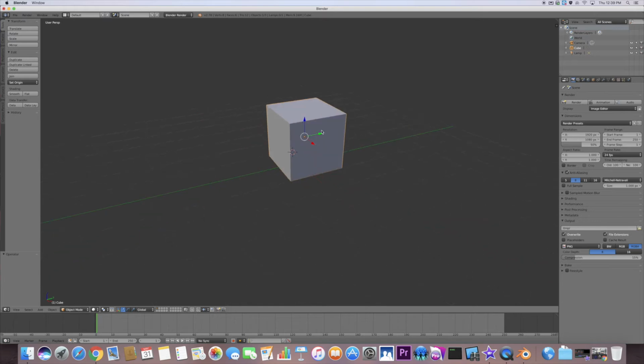The third important thing for us to do with the objects that we create is to rotate our objects. Let's say we want to rotate the object and we don't want it perfectly straight up and down. The shortcut for that, you could probably predict, is R. R will allow us to rotate the object in the axes of our choice. Again, if we just press R, it'll rotate in all axes. We have the same options with X, Y, and Z, depending on how we want this object to rotate.